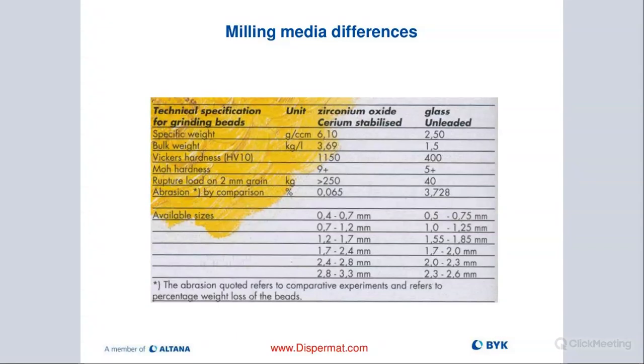You will find also that some of the suppliers on the market will offer lower cost ceramic beads, but actually we have seen that as well. If you look at that under a microscope, some of these beads are not spherical, so they actually look more like a football. And that's also something you don't want. You want to have very round spherical beads. Spend a little bit more money, and stay away from ceramic beads that are not spherical and that are more in oval shape, because they also will wear very unevenly, and that will also give you inconsistent milling results. So it's really critical that you watch out for those factors.